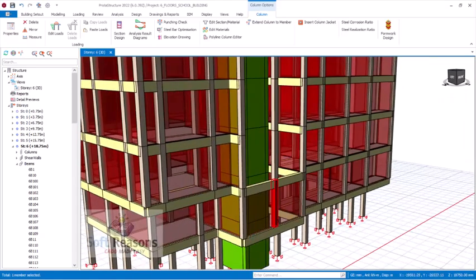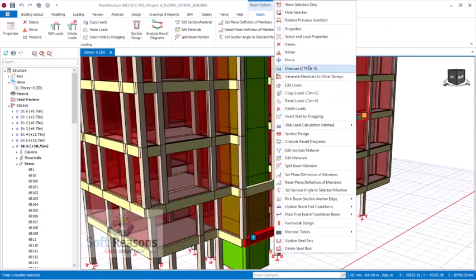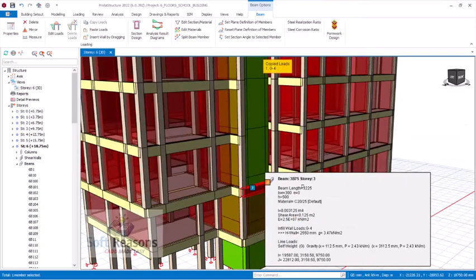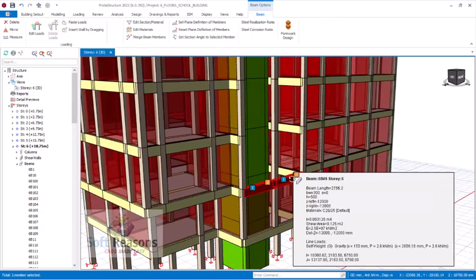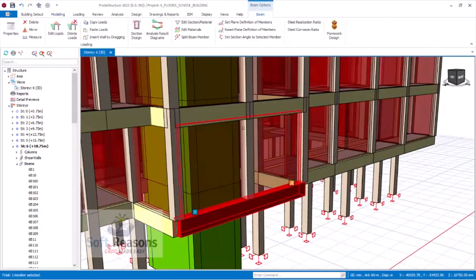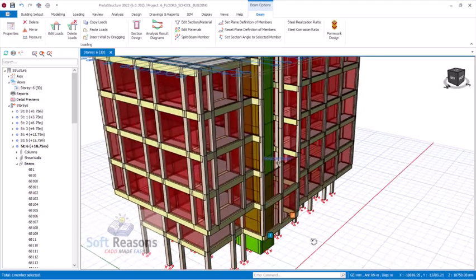Alright, at this point I want to be generating this beam, but first I'll select this one, copy wall load. I'll copy wall load because I will explain something to you now. Copy loads, options, select this beam, these 2 beams. You right click and then you have to paste the wall load. Now this beam is different from this one. This beam is more or less like a simply supported, and this is a kind of continuous beam. That is why we need to make it that way, so the load can be distributed evenly.